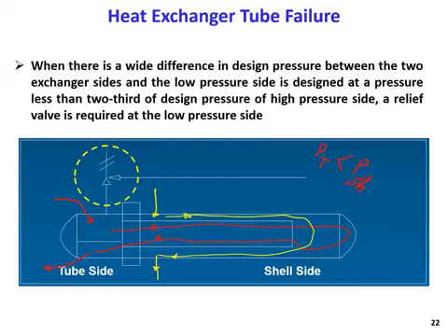Okay, this is what we have. In this case, if we have a failure here, if you don't have enough pressure in this part, we might have some operating problem. So in this case, we need to use a safety valve that can either relieve pressure from the shell side, or we can have some kind of system to add pressure to